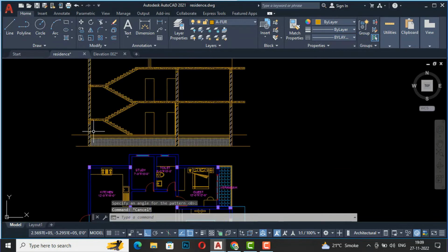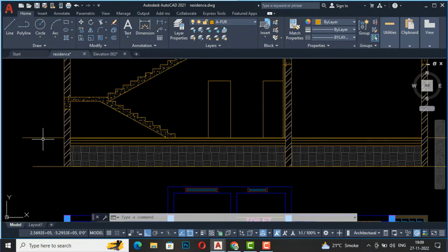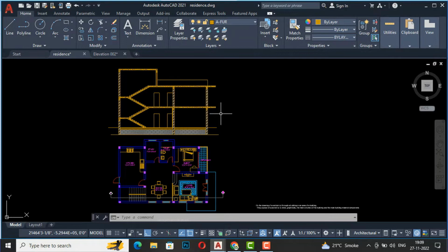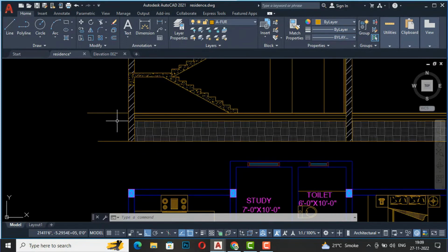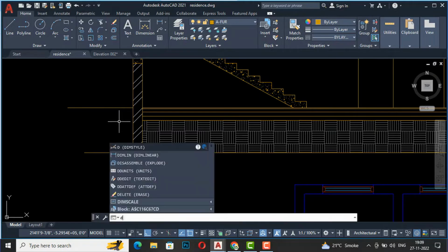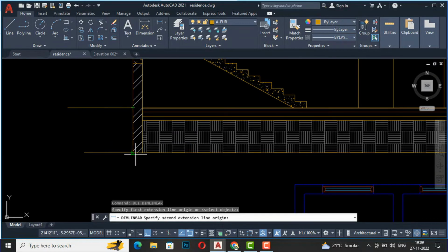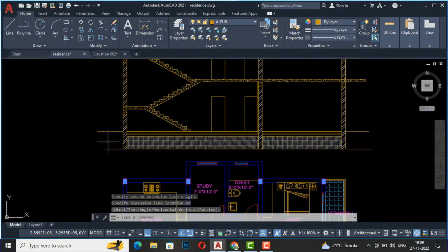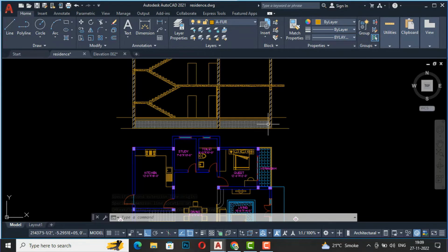So this is just to understand how to draw a section here, and you can show the plinth height here. You can show the entrance part here. If it is cutting, you can show whatever the plinth height is, whether you are taking 1 feet 6 inches, you are required to show the height here, the floor. So this is 3 feet. You can show 3 feet plinth level. You can show some steps also if they are visible in your section.